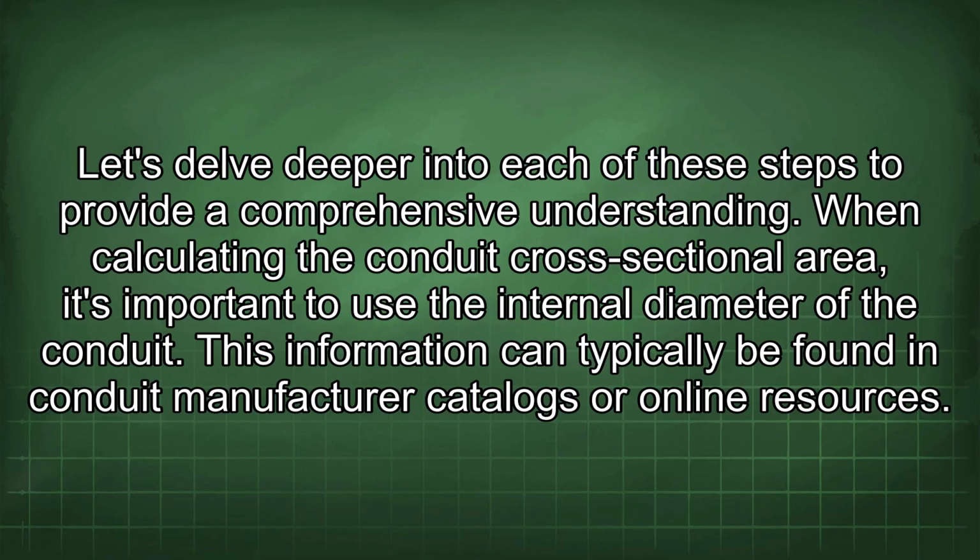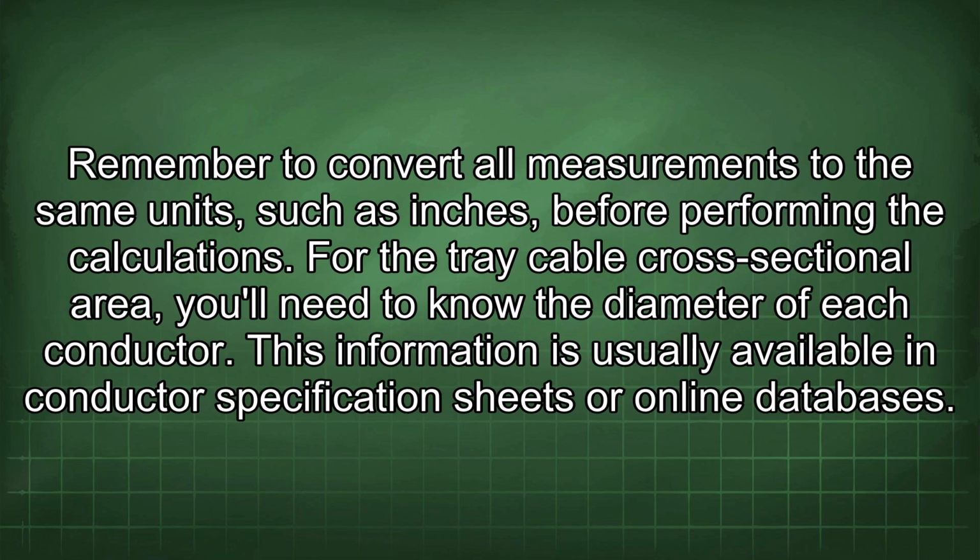When calculating the conduit cross-sectional area, it's important to use the internal diameter of the conduit. This information can typically be found in conduit manufacturer catalogs or online resources. Remember to convert all measurements to the same units, such as inches, before performing the calculations. For the tray cable cross-sectional area,